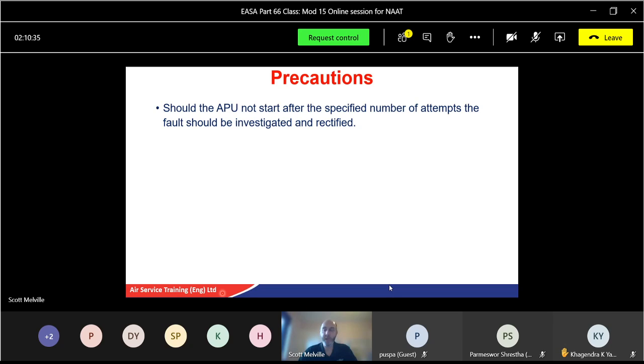So my junior came back in, big smiley face, fixed. So again, think simple first. Don't start diving into, oh, the engine's not spinning, replace it. Think simple. It could be something simple like a circuit breaker, a micro switch. Okay, follow the book. Make sure you don't just jump ahead of the game. Okay, that can save a bit of embarrassment as well.